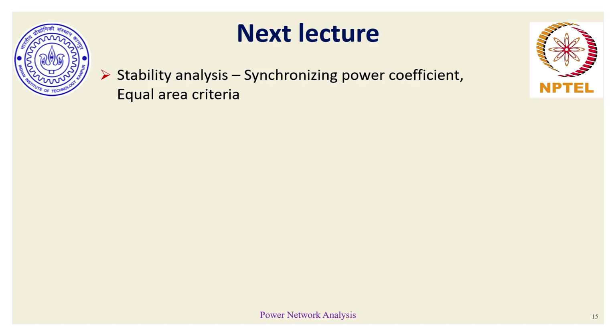That's all for this lecture. In the next lecture, we will understand the reason behind why delta naught dash cannot be a steady state operating point, and the answer to that lies in the concept of defining synchronizing power coefficient. And we'll also understand an important way of avoiding numeric integration for analyzing transient rotor angle stability analysis of SMIB system or two machine system which are either coherent with each other or not coherent with each other, and that criteria or technique is known as equal area criteria.